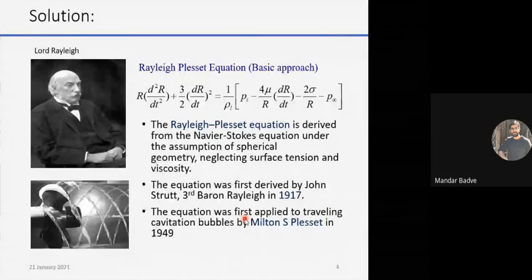that the gaseous bubbles which are present near the propeller experience a fluctuating pressure field due to velocity alterations, right? And when the pressure lowers, the bubbles grow in size, and as the pressure recovers, the bubbles shrink, and then the bubble velocity increases. And because the liquid inertia is very high, the bubble collapses, right?